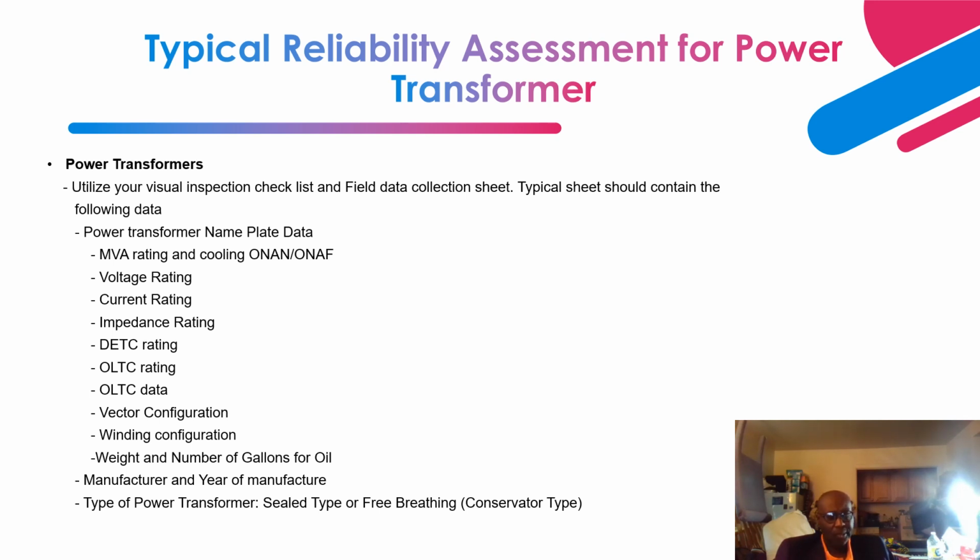As you know, the impedance rating is usually calculated, designed and tested based on the base. So you should have that impedance rating provided by checking it in the field. Next is your de-energized tap changer rating. DETC is de-energized tap changer.